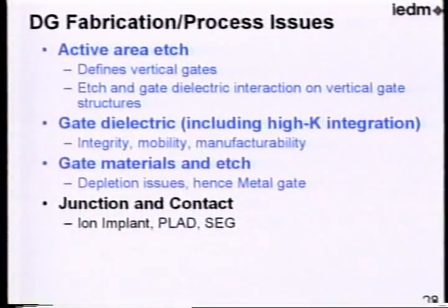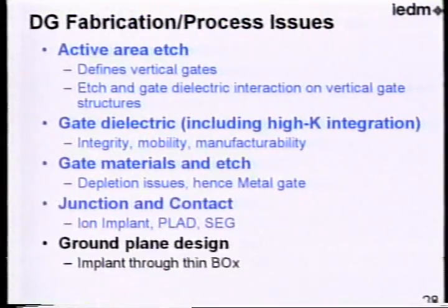Of course, you still have issues with junction and contact. Almost all of these devices, especially the depleted ones, will have a thin body. You have to use a raised source drain to make these devices manufacturable, and that brings in a whole series of issues in terms of junction and contact resistance.